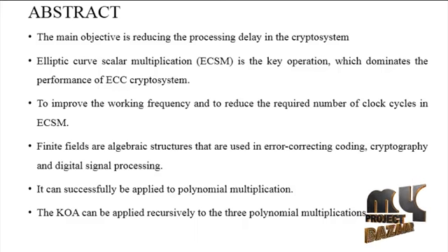Elliptic curve scalar multiplication is the key operation which dominates the performance of elliptic curve crypto systems. To improve the working frequency and to reduce the required number of clock cycles in elliptic curve scalar multiplication, finite fields are used. Finite fields are algebraic structures used in error correcting coding, cryptography and digital signal processing. It can successfully be applied to polynomial multiplication.